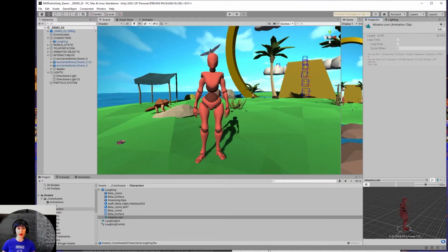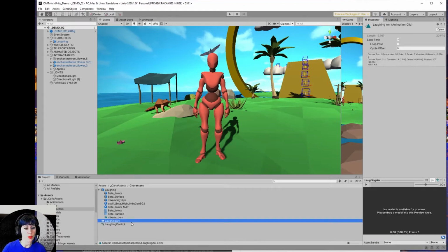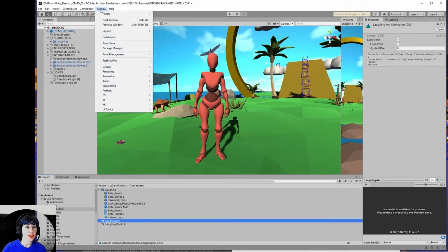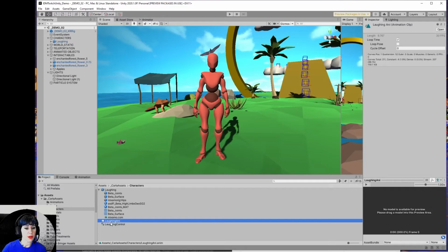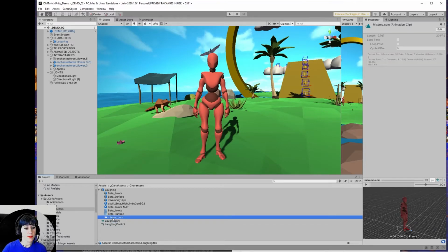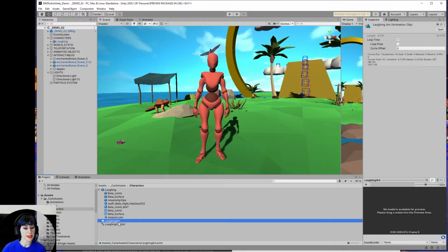And that's really awesome. There it is. Wow. But if I just drag that character to the scene, it's not going to be animated, so I have to do a couple things. One, because I like to go in and sometimes tweak or edit the animation, I will duplicate the Mixamo asset. I just press Command D or Control D on my computer, and then there's the animation. Then I have to create something called an animation controller.